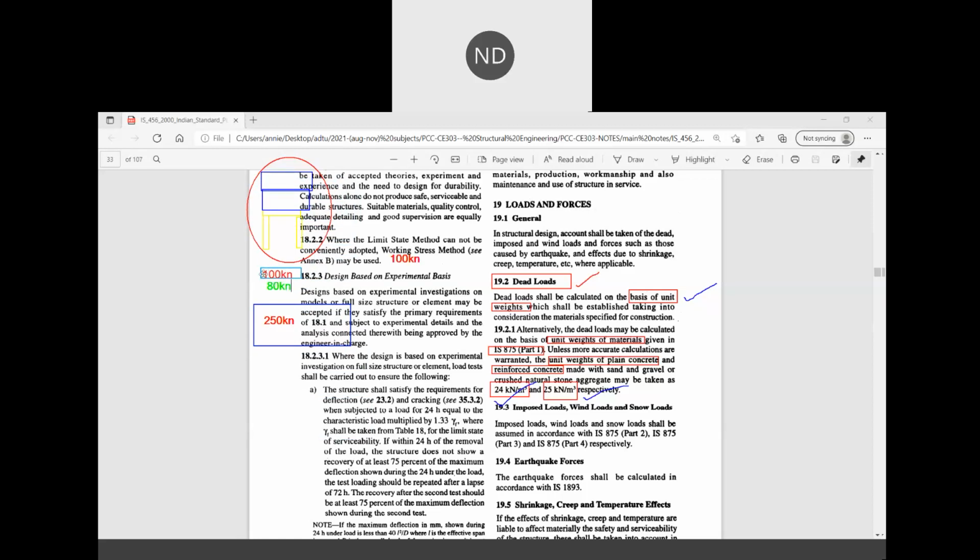And further 20 more kilonewton of load it can carry extra load, so no problem to us. So we can use this load here, right? As compared to this, what is the disadvantage if we use this over this beam? The disadvantage is that the structural weight of this particular member is going to increase, and as this load increases when we place it here, the entire structural load will increase, right?